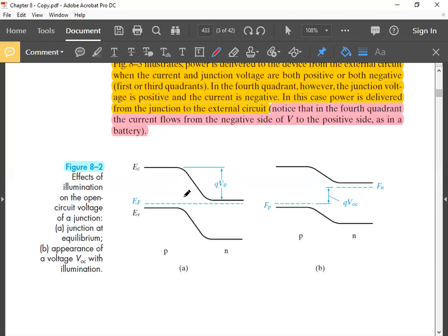because you can see when you form the PN junction, the Fermi levels are being aligned. Because of that, this shift is there. The difference between the conduction band of N side and P side is determined by the shift of the energy bands in order to align the Fermi levels. And this amount of shift, obviously you can see, is less than Eg.